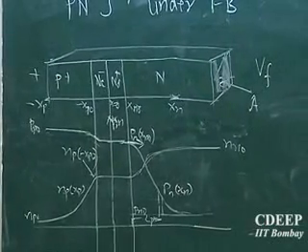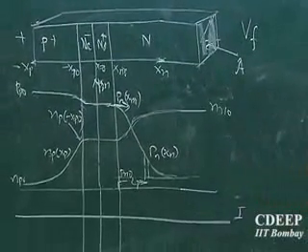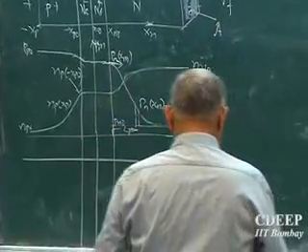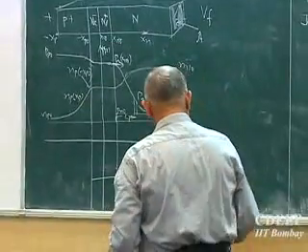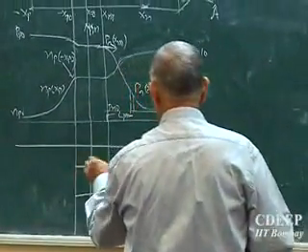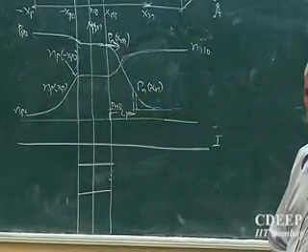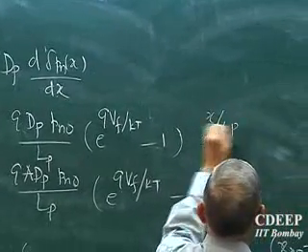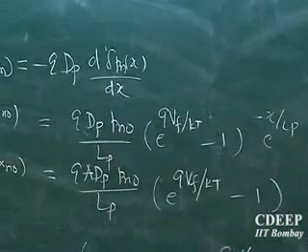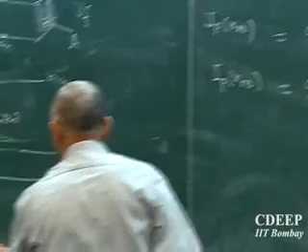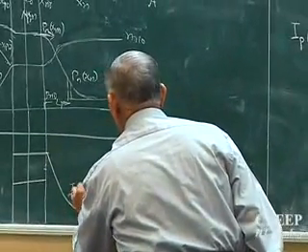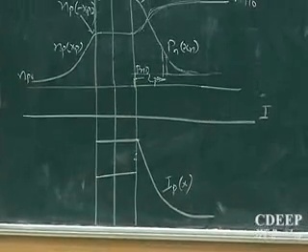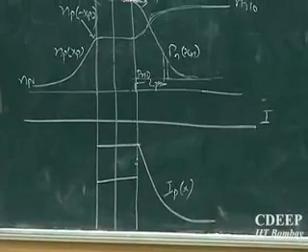So what does that mean? That I got this current, let's say I is the total current across the device. At this boundary, wherever I have, maybe I put it something like this, the current at two boundaries, from here it goes down by how much? By this relationship. Please remember this is at x_n0, but at x, an e to the power x by L_p term will appear. It will start decaying the current as I increase the distance. This is my I_p(x) current. Is that clear? As the carriers decay, the current will correspondingly go down, with e to the power x by L_p equivalent terms.